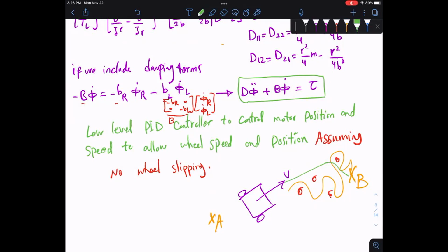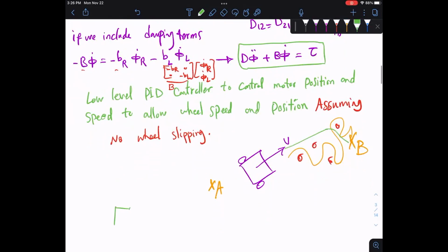So now for odometry here, usually the DC motors come with encoders, so they can tell you what's the position, what's the velocity, right? So that's from the encoder. First of all, there might be some error in the reading, right? What else can go wrong? Because usually, do you expect that you just go on a straight line? You probably say, I was going to go on a straight line. This is the velocity, but this happened. I ended up getting where I wanted, but I wiggled a little bit on the way, right? What could cause that? One was the resolution of the encoder on your DC motor. What else can happen that the car will deviate?